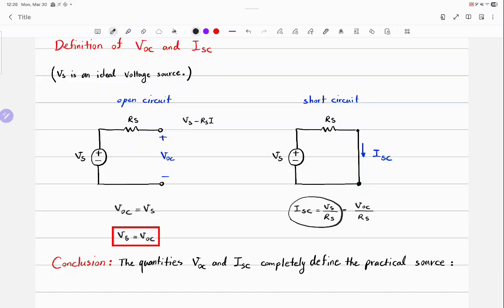What is Vs? Do I already know it? I just measured it, and it's 10. So I can replace it with 10, 10 being the open circuit voltage. Okay. Did that make sense? We can discuss it after I'm done, okay? If you're still not satisfied with it. Okay, so instead of Vs, I wrote VOC over Rs. Now, I'm going to rearrange this and write it like that.